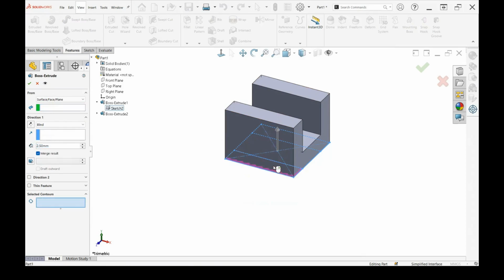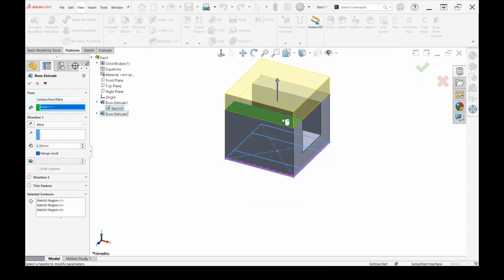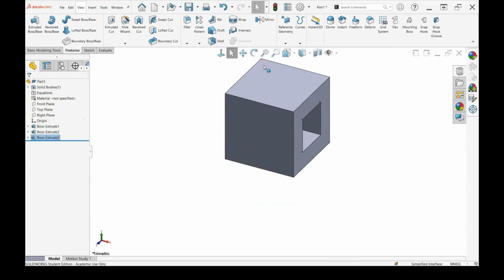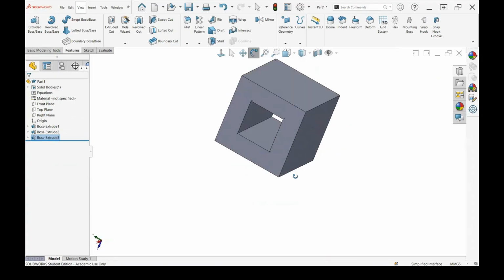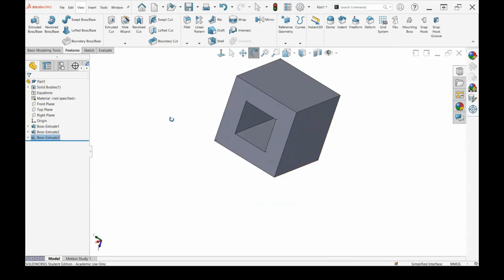And selected contours, again, we're selecting the various different 3 regions. Our new surface plane that we're extending from can be either of the rectangles that are the new small faces up here. And that's now option number 3. So we can select our little rotating tool, peek in, nice and even, and then follow the same procedures of the drawing creation that we talked about before.